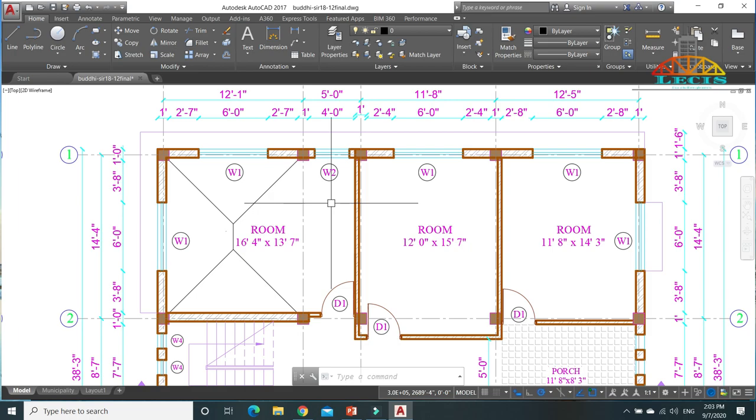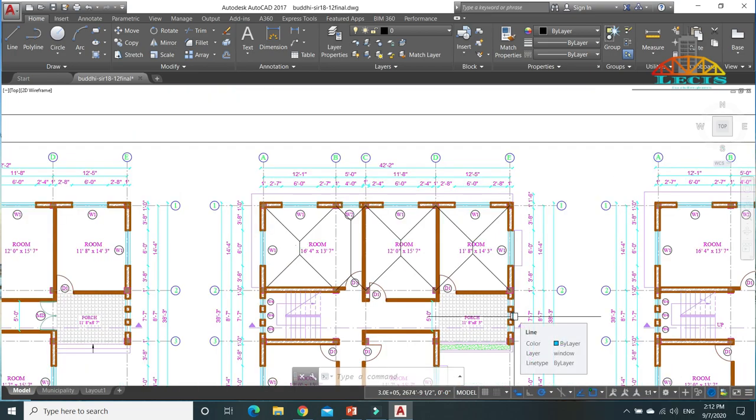And finally, this will look like this. You see here that end lines are drawn on every slab panel. This beam takes this trapezoidal area. This beam takes this triangular area. Similarly, here this beam takes this trapezoidal area plus this trapezoidal area from this slab.